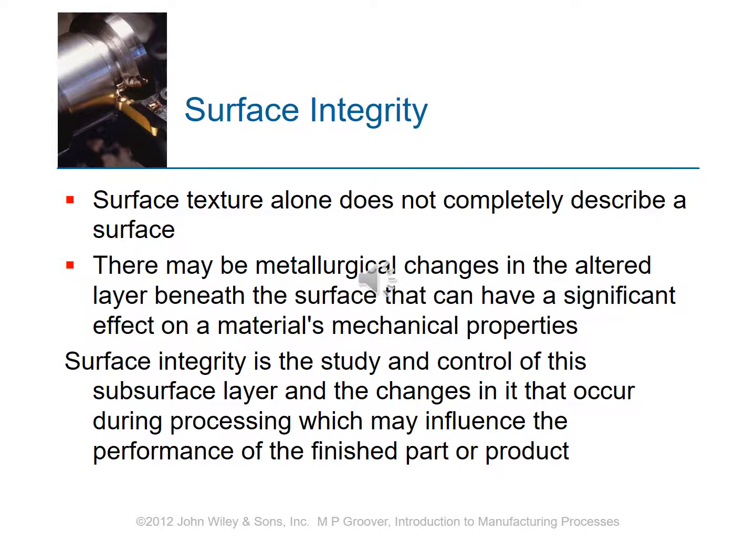Now, integrity. Again, we're talking about little defects in the material, and this is where stress will come in and concentrate. If you have a lot of defects and flaws in your material, it's not going to last so long. Think about a cheap tool. It's not the best material, with a lot of defects in it, and it doesn't last so long. Get an expensive tool, it's got a little bit better material in it, and lasts forever. This is because of the integrity. So you're controlling those defects and the characteristics of that material, and you don't want to screw this up during the processes, so you have to be real careful.